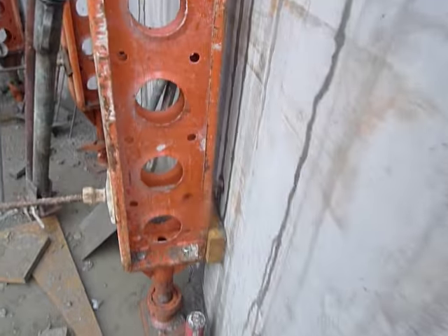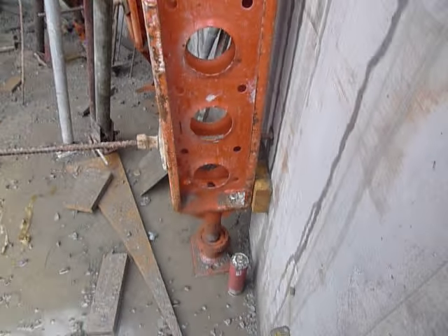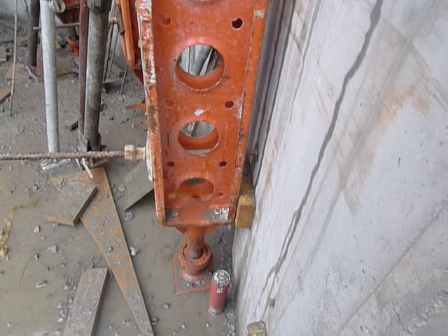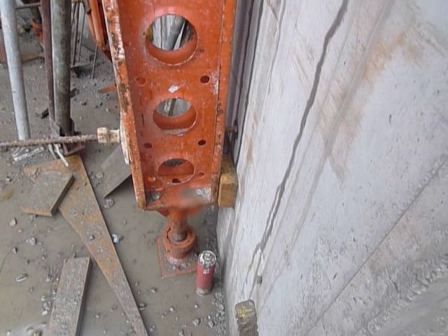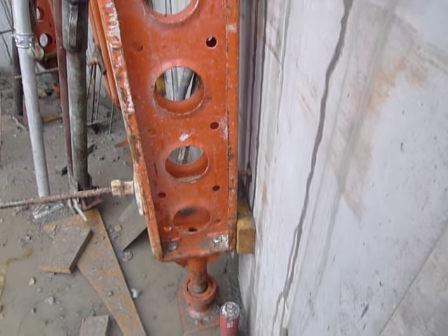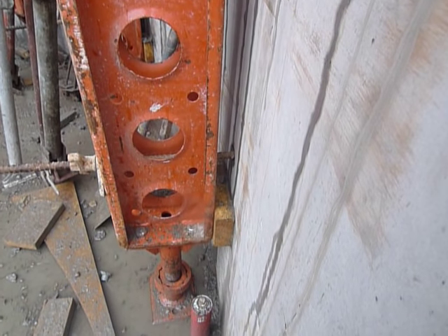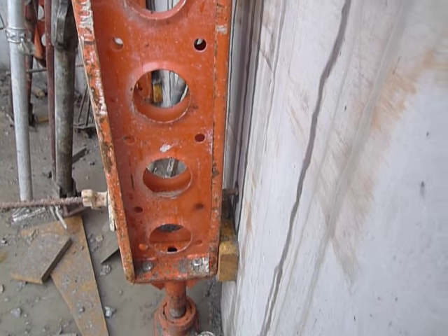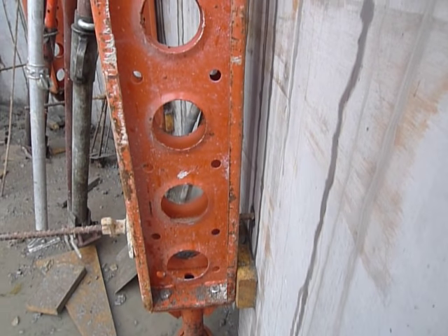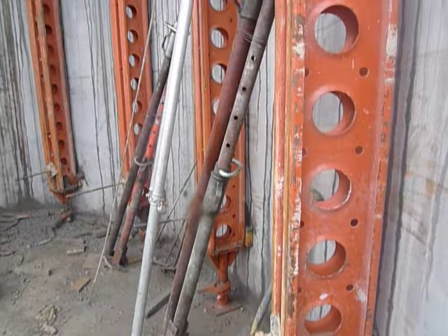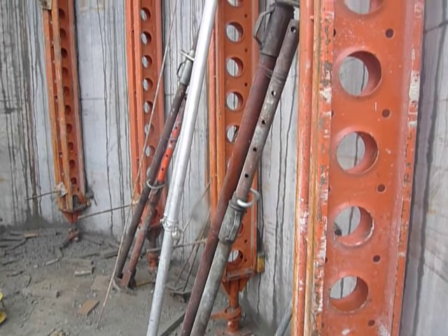Okay, that's where the adjustment is made. It's made at the bottom of the strongback, and the packing is just below the walings. Ideally it should be 50mm, so that one there, as you see, is 45mm, which would indicate we had to pull the shutter inwards 5mm. And generally it all worked too well.